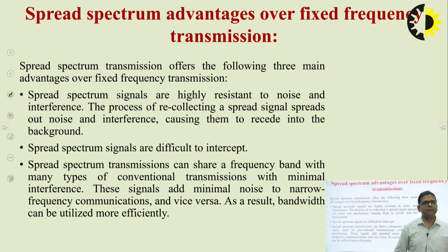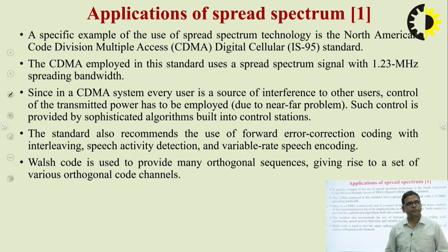The second advantage is that spread spectrum signals are difficult to interpret. The third and important advantage is that, using the spread spectrum technique, a particular frequency band can be shared by many users or sources. This is the major advantage of the spread spectrum technique.